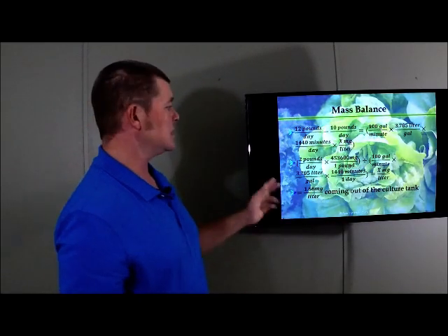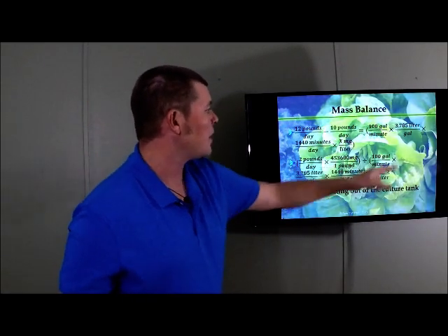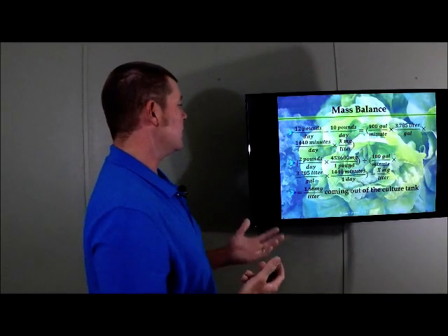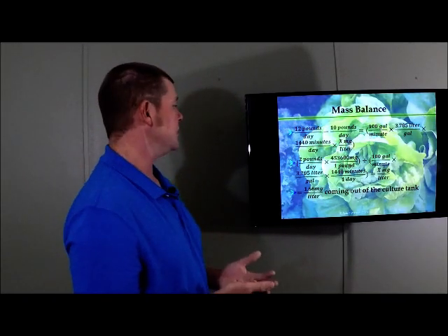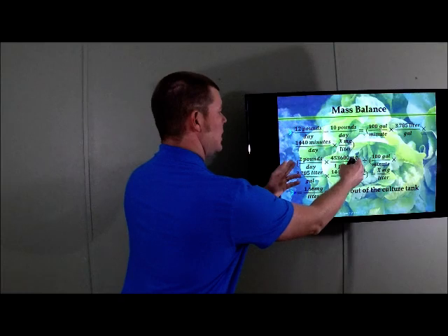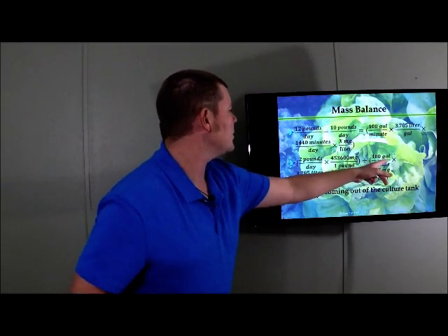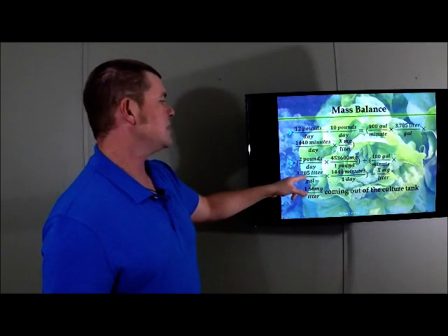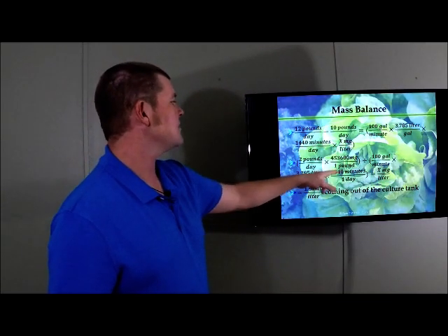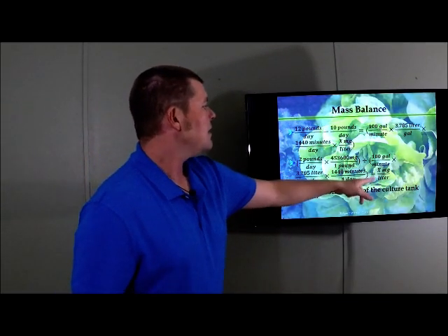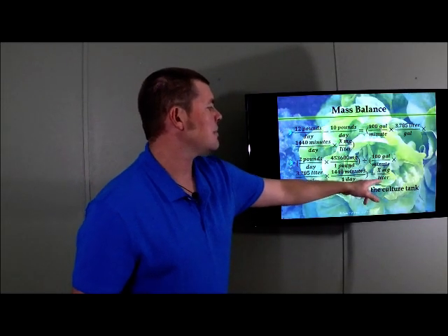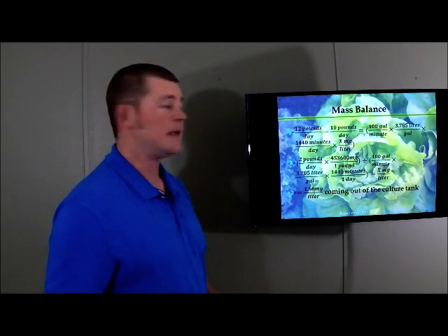And unfortunately, it's such a long equation, I can't get it all the way across there in one line, or it gets really small on the screen. So we do this area of the multiplication, and then we divide that by 100 gallons per minute times 3.785 liters per gallon times 1,440 minutes per day. And that's going to give us how many milligrams per liter of oxygen are leaving the tank.